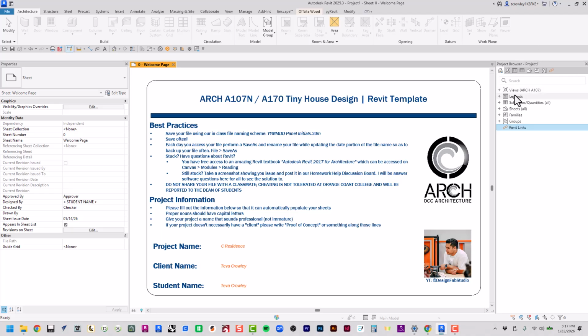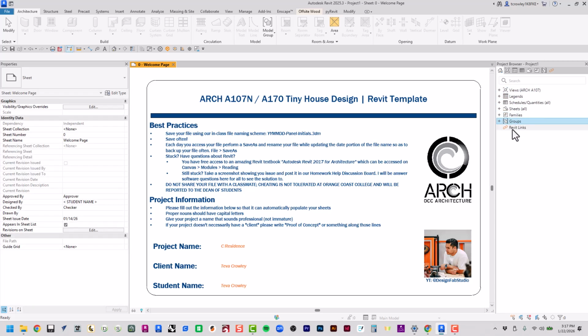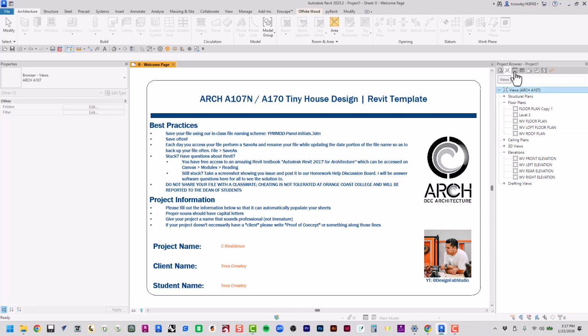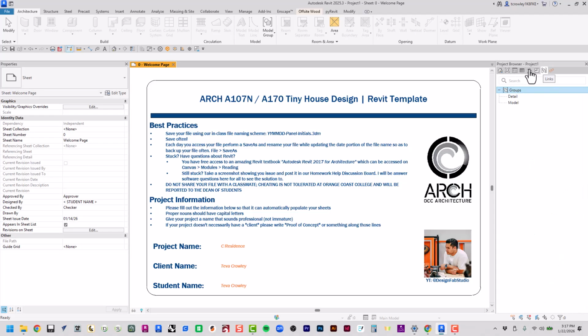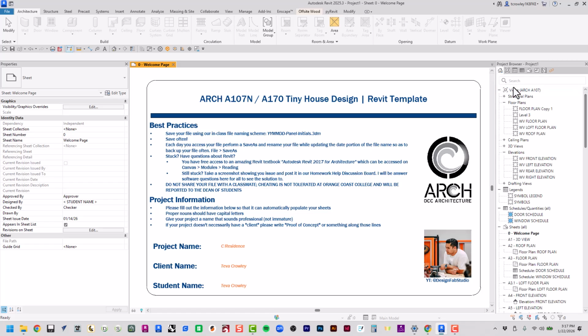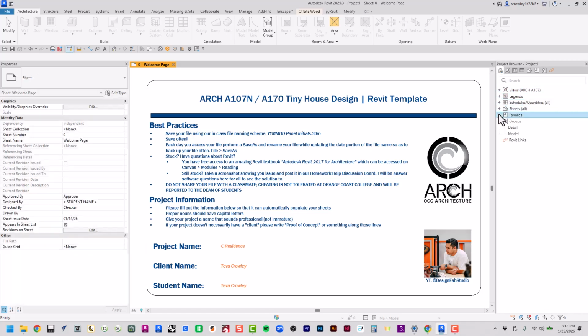So these are the different categories, and in Revit 2025 and newer, in our project browser, they've added new tabs here at the top, which basically take each one of those categories and gives them that whole entire tab. So either you can have all of those categories listed here on the Home tab, or individually. So here's Views right here.